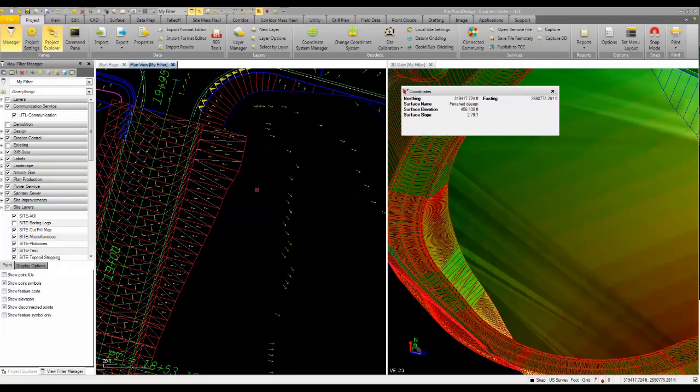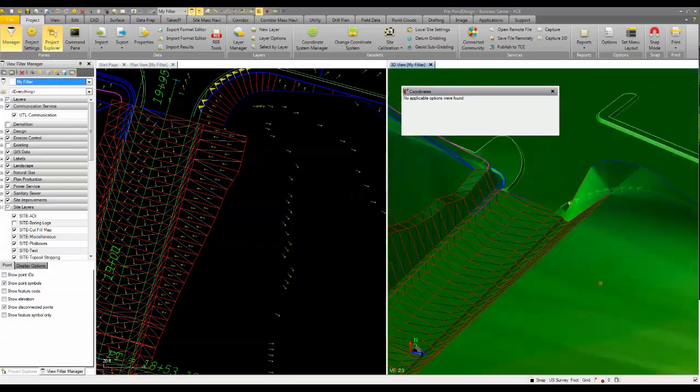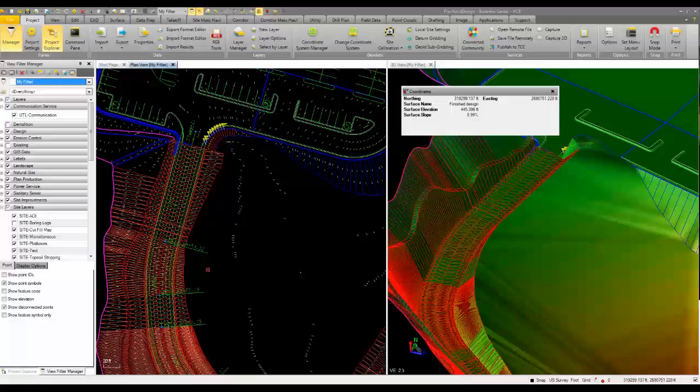So what we're going to do is run this off at the same 3-to-1 slope from the hinge. So instead of having this ditch that we have up here originally, we're just going to go from the shoulder, and we're just going to go straight down into the top of our pond.